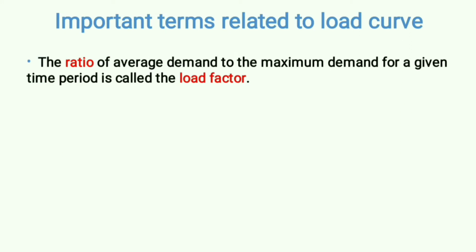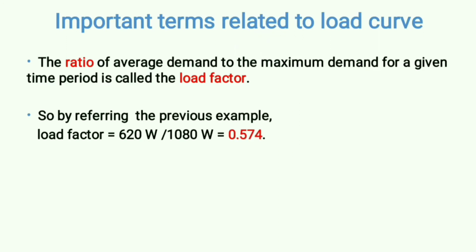Next we'll see load factor. I have already explained this in my previous video lecture. It is nothing but the ratio of average demand to the maximum demand. Again referring to the previous example, 620 watt by 1080 watt will give you the load factor.